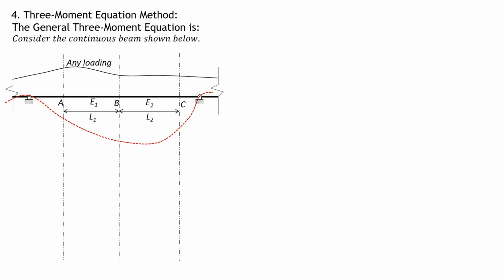So this is the elastic curve. Then from point B, we draw two lines. One is the tangent line and the other one is a horizontal line, which serves as the reference for computing the displacements at A and C. So this is the horizontal line through B and another line at B on the elastic curve, the tangent line. So that we have two similar triangles, this right triangle here and another right triangle here.